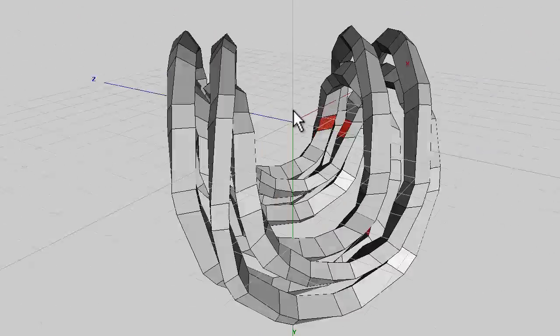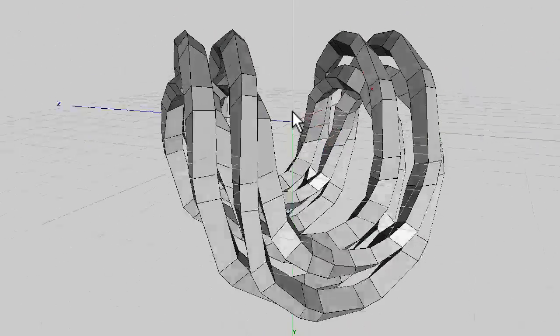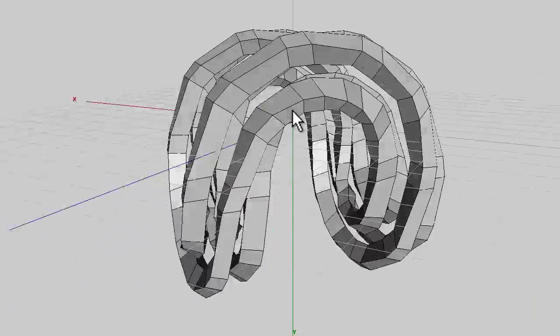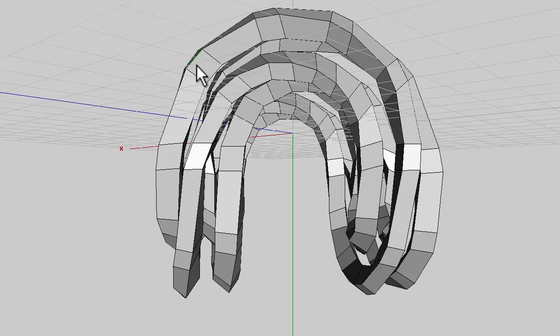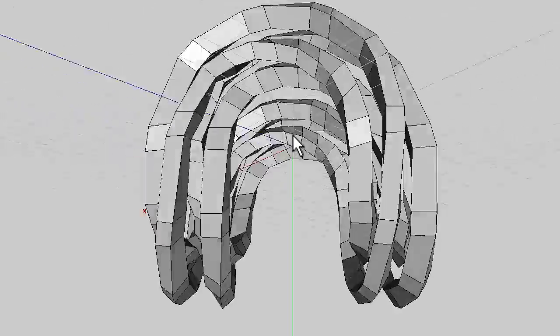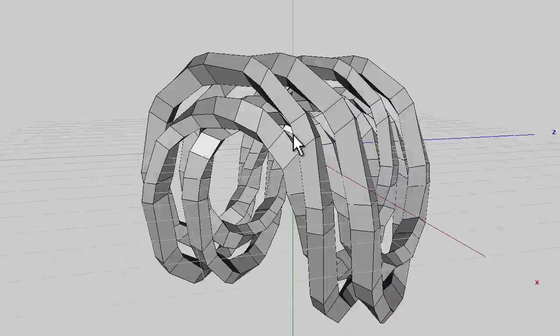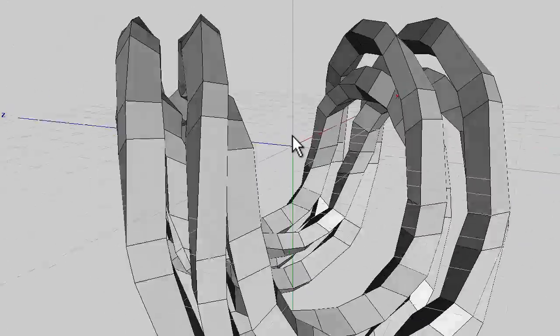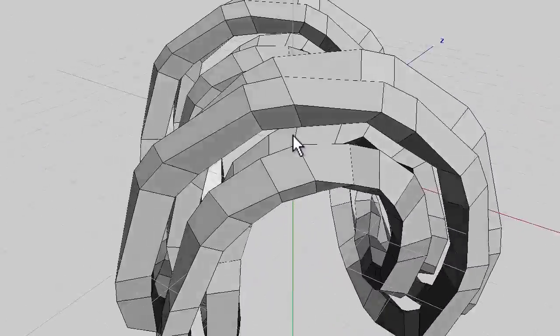Right, now we've got these 4 elongated ones, and what we're going to do is connect the opposite sides to one another. Now you will notice where the ribs were connecting the edges of the cubes that were in the wireframe, they're of even spacing and the other ones are of odd spacing. So you want the even spacing ones and you want to bridge the opposite ones of the even spacing ones, which is where things get a bit fiddly in the old wireframe view.